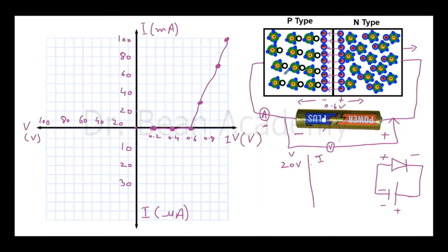It is always the case that there are some electrons on the p-type side. You can call them leftover electrons, or these free electrons are actually generated on the p-type side. Ideally they should not be there, but sometimes there is a breakage of covalent bonds, or due to some manufacturing processes there are some free electrons, and the quantity of these electrons is very minute. So just remember that one.